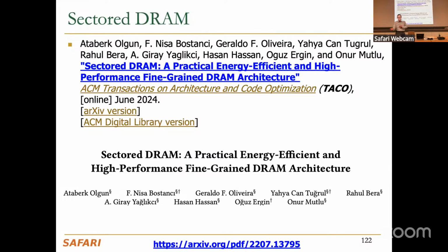Okay, this is the fine-grained DRAM architecture that we could use. There's a lot of work in this area, actually. People developed this fine-grained DRAM for other reasons, meaning you access a huge row, and in the end, you need only 2 bytes out of it. Why do you access the entire row, right? That's a lot of energy inefficiency.